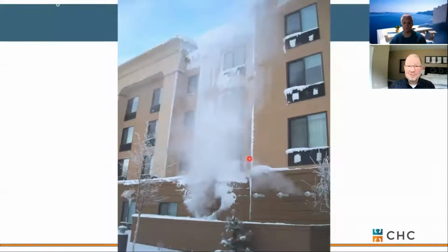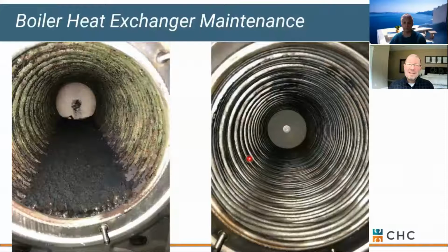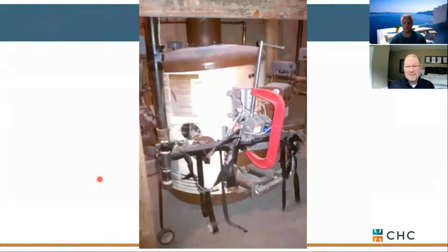But they're all challenges. Maintenance is another one. We see a lot of guys who want to go high efficient condensing these days. It all makes sense, but you have to maintain that equipment on a regular basis. Otherwise, efficiencies aren't very good. All these are challenges to our industry. Ultimately, the mindset is, let's put something in a closet and come back in 10 years and check on it.